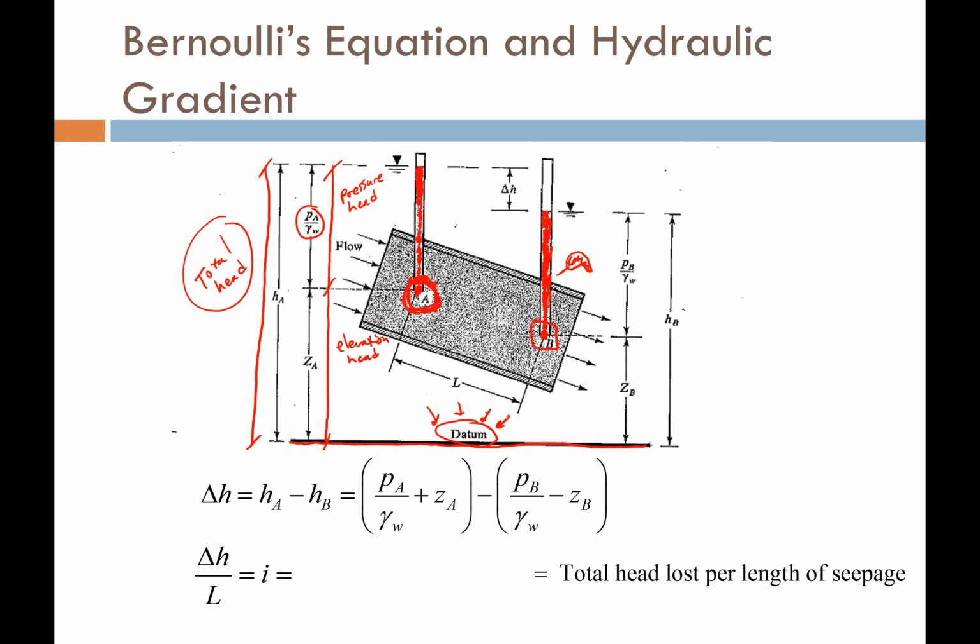Now here's the interesting thing. I can do the same thing, okay? The total height from the water surface in my piezometer down to my datum, and remember, it has to be the same datum. That's the rule. So the height from my water down to my datum, that again is total energy. And the depth from the top of the water down to my point of interest, that is my pressure head. And the height from my datum up to my point of interest, that's my elevation head.